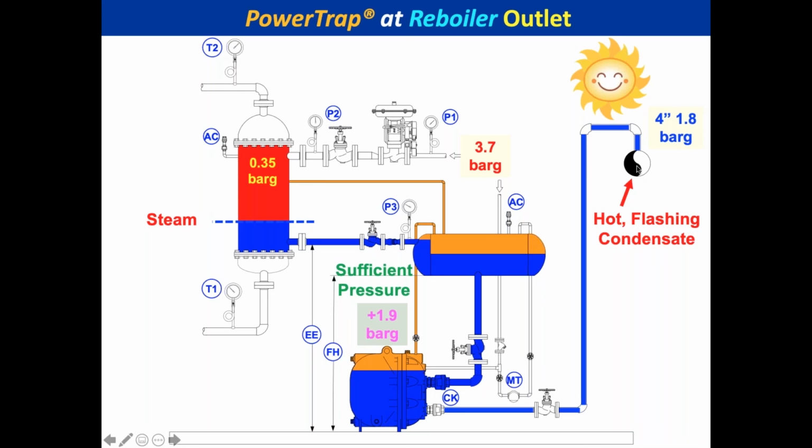Because the side, it'll hit the liquid condensate, and I wouldn't bullhead it in at 90 degrees. I'd come into it here at a 45 degree and let the flow go in the direction of the flow. And that way you're less likely to get a collapse from swelling of condensate there if you bullhead it.